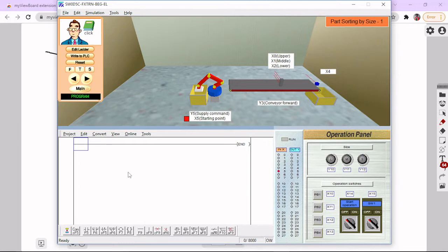So it begins to operate just like you would when you are working with a live PLC. So for instance, F5 here is a normally open contact, F6 is an open contact branch, and SF5 here is a normally closed. So you can just pick this normally open contact. Now it has to have an address. So here we have X10, X11, X12, X13, X14, X15. So I have to address this contact to any of these. If I'm addressing it to X10,